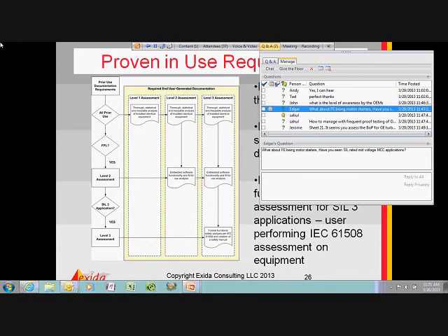Here's another one from Edgar: what about final elements being motor starters? And have we seen SIL-rated medium-voltage MCC applications? I have seen applications that require the motor starter to be successful. I'm not aware of any SIL-rated ones yet.